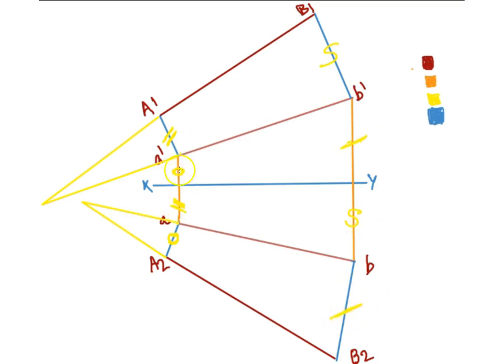So if you know one of the views, or if you draw one of the views, you can immediately draw the true length on the other side by projecting the points perpendicular. The only thing you need to consider here is this should be perpendicular to the view. Similarly, this should also be perpendicular. All these lines are perpendicular. So basically it's kind of a trapezium. It has two parallel sides and two sides which are inclined to each other.